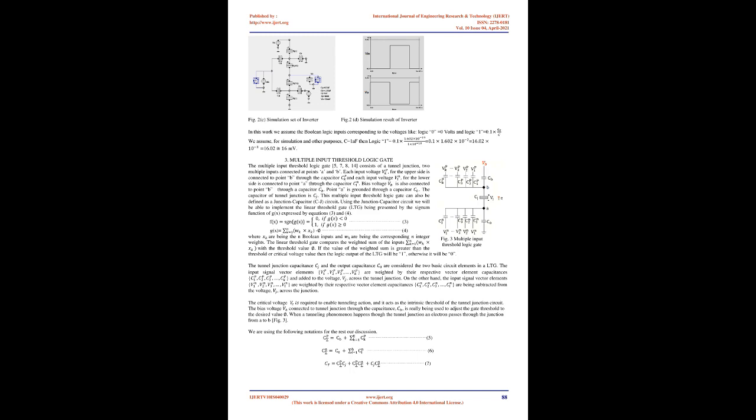If a single electron tunnels through the junction, the tunnel capacitance is charged with an elementary charge, 1.602 times 10^-19 C, building up a voltage V equals e/C, where C equals the junction capacitance. When the capacitance of the tunnel junction is ultra small, the voltage building up in the tunnel junction may be adequate to prevent another electron from passing through. The electrical current is suppressed as the bias voltage is lower than the voltage created in the tunnel junction, and the resistance of the device will no longer remain constant.